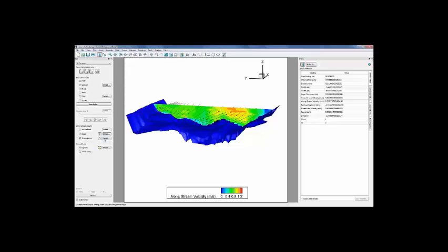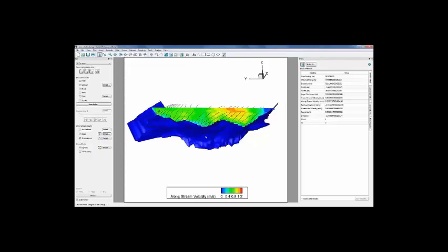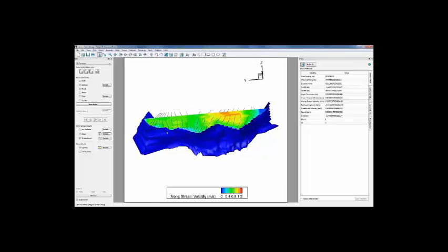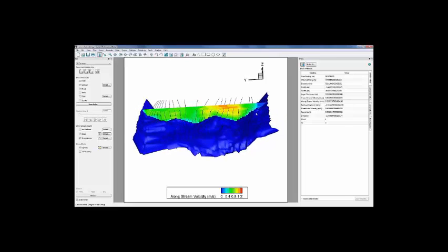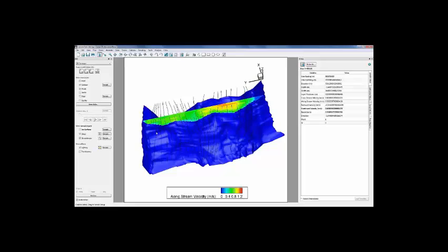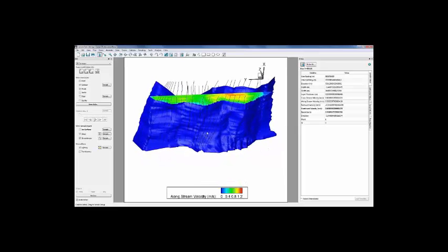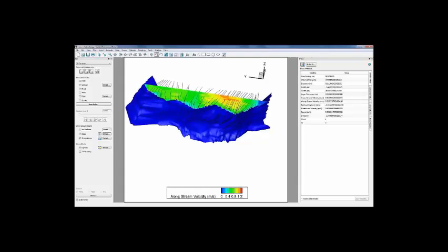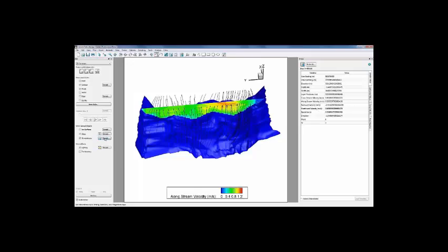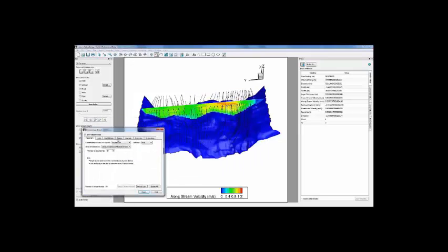Okay, thank you, Art. And then one other key thing that you can do in the Cubeit environment when you have the volume data is actually look at the streamlines. Here we actually have the X and Y velocity components, so we can interactively seed streamlines throughout the subcubes to better understand the flow field where you're getting certain mixing, if that's of interest to you. So here we're kind of just dropping in some seed lines, and we'll turn on some timing markers in a second. But I'll hand it back over to you, Art, because analyzing the flow field throughout the volume can be very effective.